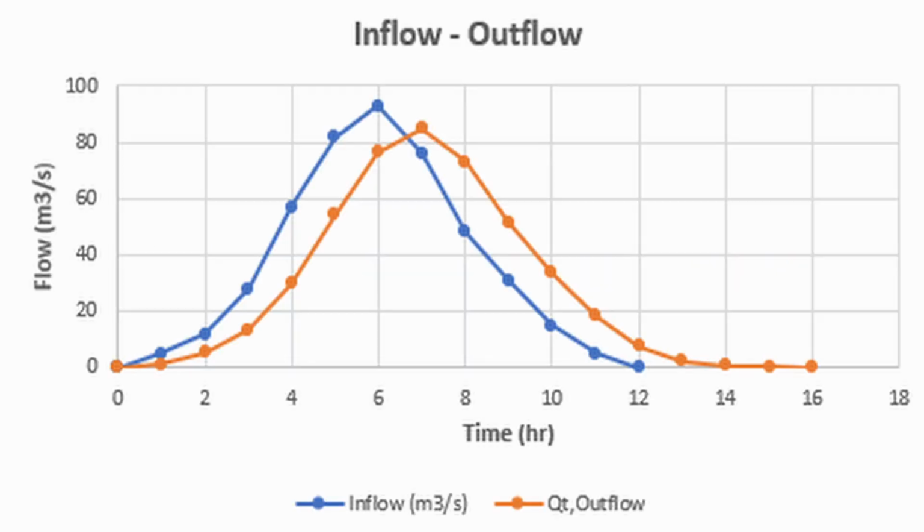Once that is done, we convert the rainfall into excess rainfall, because not all the rainfall that falls into the catchment is taken out as runoff. We can apply various methods like the SCS method, which helps us come up with the excess rainfall the catchment is going to undergo. And through that, we are able to generate the PMF hydrograph.